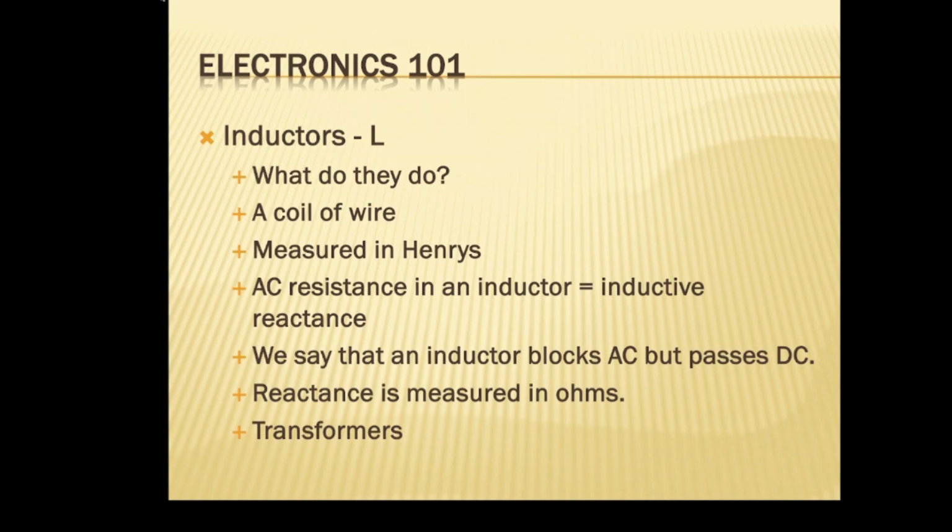Well, antennas is probably one of the biggest places that we see that as amateurs. When we measure our SWR on the antenna, we have true resistance, the resistance of the wire, the elements, whatever. And then we have the capacitive part and the inductive part. A lot of the antennas have a coil of wire on the bottom to make it look like it's longer than it really is. That's an inductor. So we have inductive reactance involved. A lot of antennas will add a capacitor to tune out some of that or nullify some of that. So we have inductance and capacitance involved.